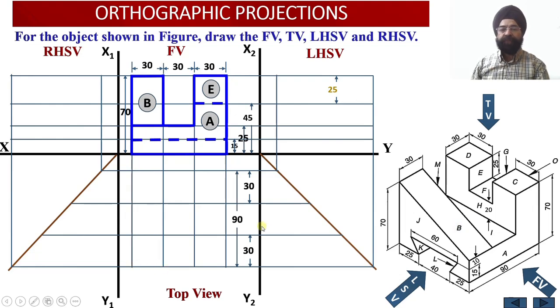The projections of surface B have been obtained, projections of surface I have been obtained, projections of surface D, F and C have been obtained. So out of these 5 surfaces, projections of surface B are apparent projections, whereas the projections of surfaces D, F, C and I are the true shape projections. So I am left with these 2 slots over there.